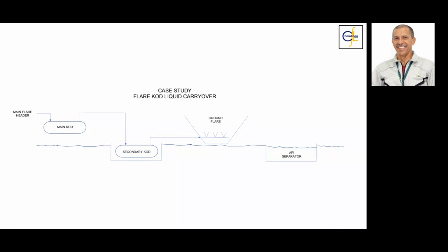And somebody said, okay, as the flare knockout drum is never in use, we can allocate this volume temporarily in that drum. What happened? They bypassed the operation of the pump, and they included that extra volume of liquid, and then they went higher than the maximum liquid level, because it was a temporary solution while they solved the problem at the alkylation plant.